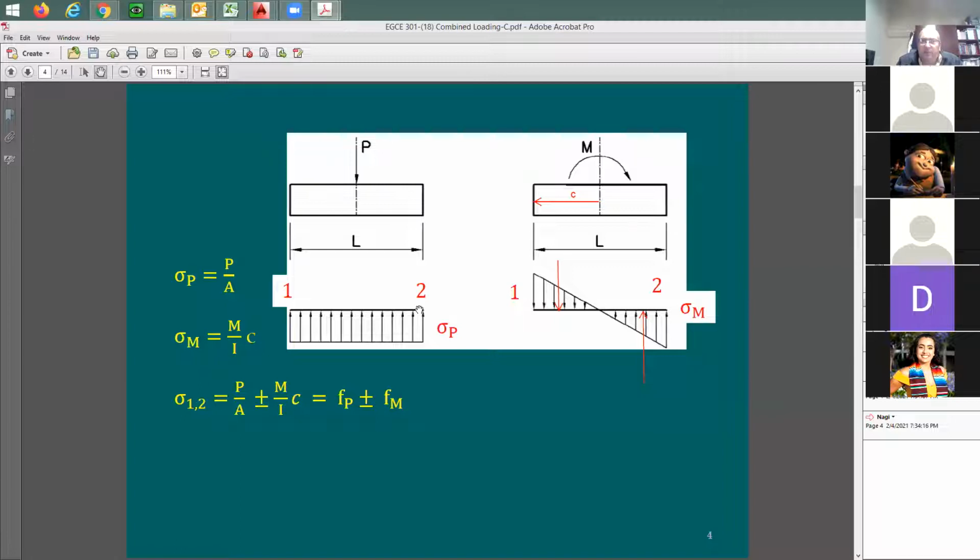But later on, once we start to do our prestress analysis on given sections, we really need to keep track of the sign. From time to time, we're going to go into the equation and see if this is tension, and then we say, yeah, tension is positive, this makes sense, compression is negative. Is this really tension or not? Or did we make a mistake in our formulation? So this side here is going to be subtractive, and side 2 is going to be additive because it's compression. This is also compression.